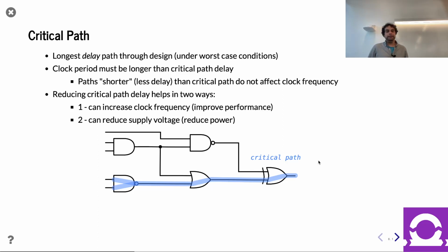So it depends. But for the most part, as hardware designers, we're very focused on this critical path because it sets a constraint on the clock frequency, right? Depending on how much margin you put beyond the critical path for frequency, sure, but this still sets the clock frequency. And so if you can reduce the critical path, what happens? Well, you can increase clock frequency and go faster, or actually you can turn down the voltage. If you turn down the voltage, the circuit goes slower but takes less power, right? So if you have a certain performance constraint and you have the clock frequency to meet that, but you can shorten the critical path, keep the same clock frequency, turn down the voltage, and save power, right? So you really want to optimize the critical path.